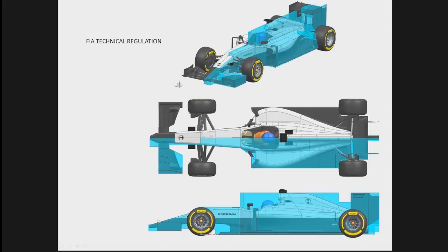If you make the nose shorter, effectively what you do is you take this point and you move it back up to about here. So you don't have a nose over the FIA section anymore. You clear what I call the FIA section, we understand is this piece of front wing in the middle. So you clear the FIA section from having a nose over it, so you don't have this sort of section problem anymore. And you still have a section, but effectively a bit higher. So there's a sort of bigger mouth for the air to go under the nose.